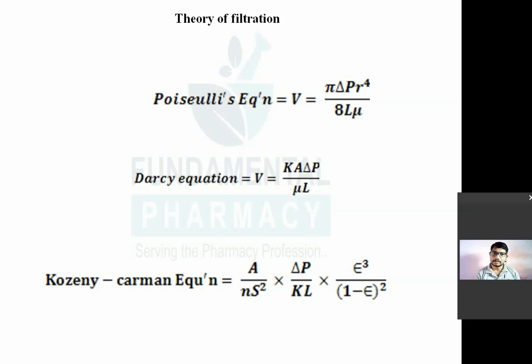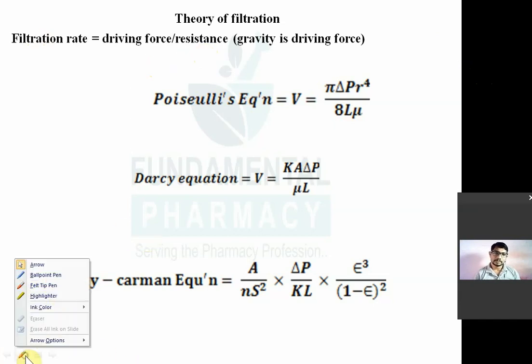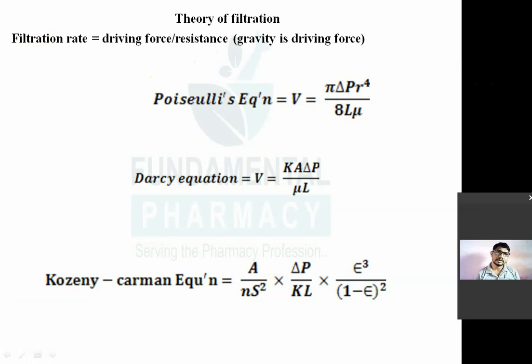Okay, now what is meant by resistance? Your filter medium will resist the filtration. It is nothing but the support, so it will resist the filtration. So driving force divided by resistance is nothing but the filtration rate. And if you are not using any external pressure, in that case the driving force is nothing but gravity.